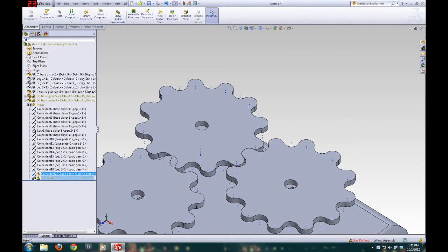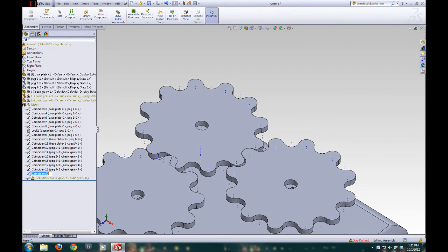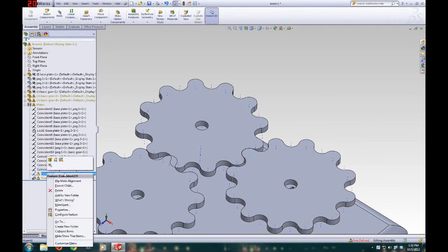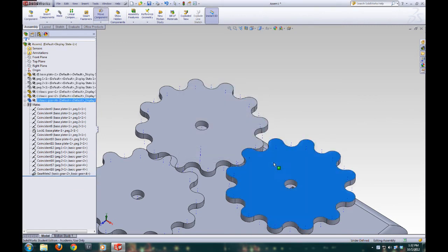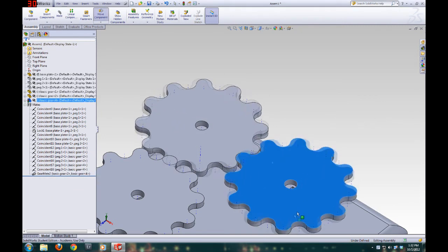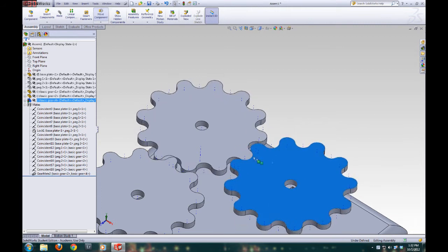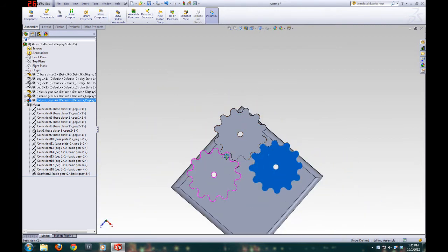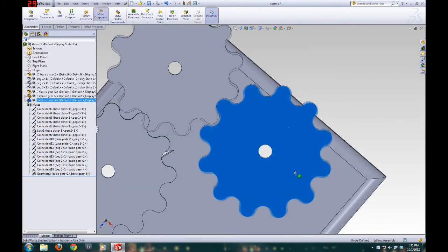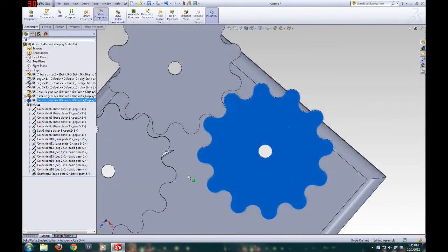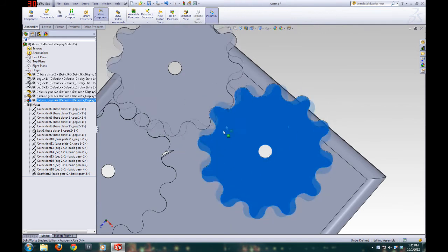If we go back to the coincident 27, this is one we made between the two axes. We just go back and delete it because it's without purpose now. All of a sudden we can rotate again. The gear ratio is proper, and since they rotated a ratio of 1 to 1, since they're the same gear, they mesh perfectly. Look at that. Now you've got the gears going nice. So hopefully this is straightforward.